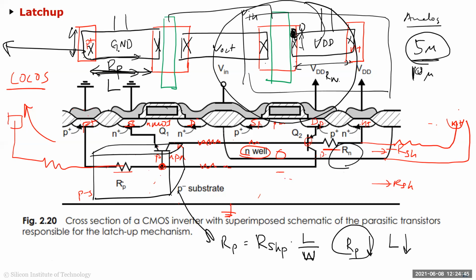How close? Nobody knows. Nowadays people do a lot of this, because it's dependent on so many things. It depends on how thick your W is. If you have a really wide W, then you could live with a longer L, but you don't know that, because this is all decided in the layout. But there are certain rules which people have found out throughout the years, and they are included in DRC.